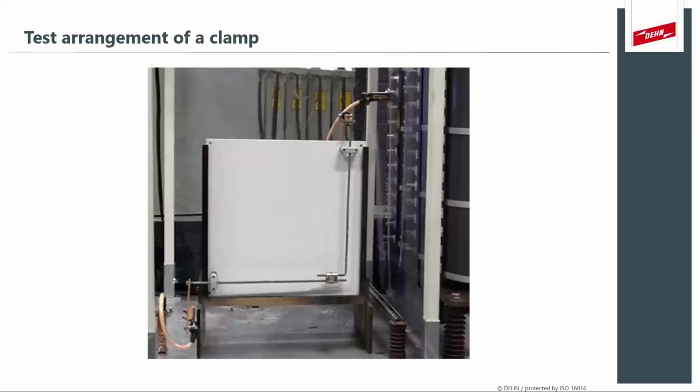And they do a mechanical force strength test. And at the end of all these tests, when the clamp is heavily corroded from saltiness and sulfurous atmospheres, and pulled around a bit for the force test, it still gets injected with lightning current to ensure that the clamp itself will safely conduct the lightning current through the components that it's actually connecting, and then it will receive a pass.